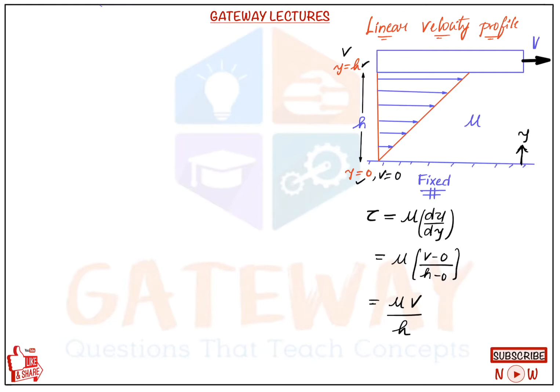As we move to the top, v increases and also h increases, and they both increase in a linear fashion, so the slope remains constant. At some point A, somewhere point B and somewhere point C, even though the velocity of A is not equal to the velocity of B is not equal to the velocity of C, tau of A is equal to tau of B is equal to tau of C. The shear stress is always the same at each and every point in the fluid for the linear velocity profile. This is the important thing for us to solve this question.